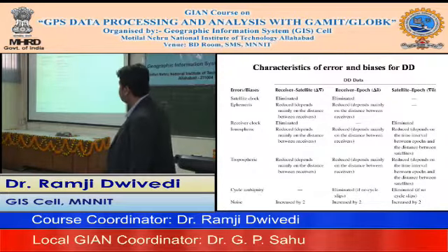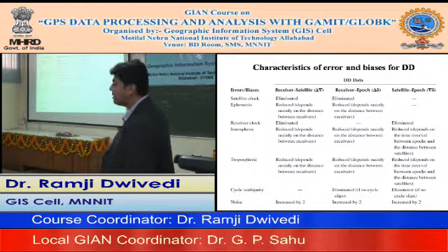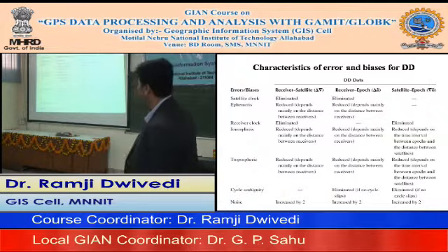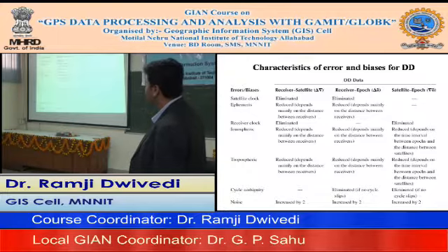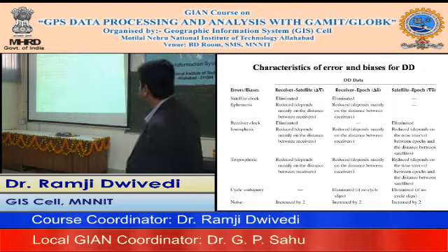But what will happen, in summary? Satellite clock eliminated, receiver clock eliminated, ephemeris reduced because of orbital error. You are taking both satellites into consideration at a time, and you are taking the differences. Ionospheric error is again reduced because it depends on the satellite baseline length, and noise is obviously increased by 2, because you are eventually going from 4 to another estimate.